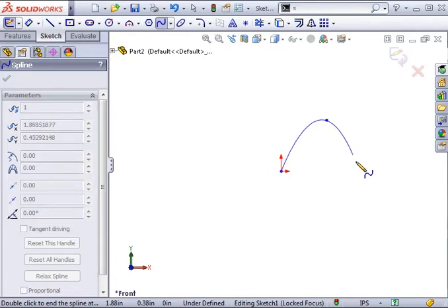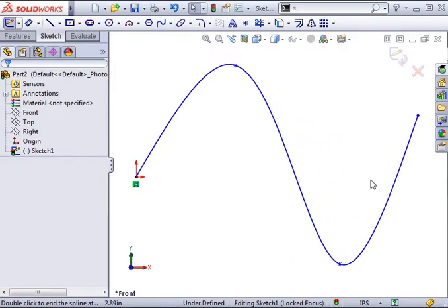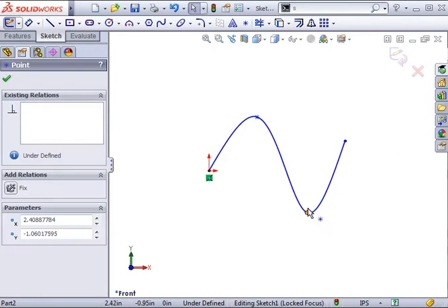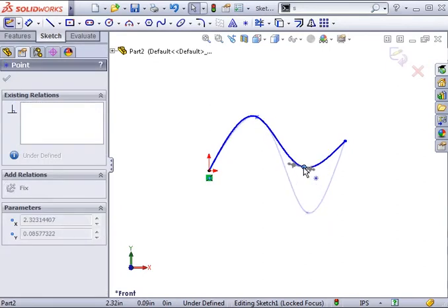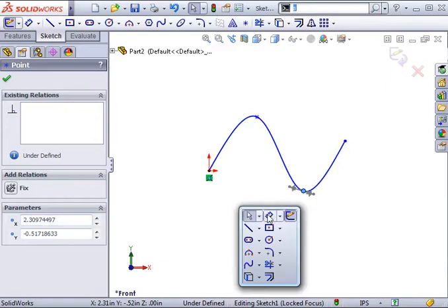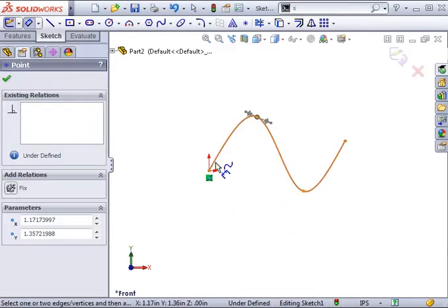You can leave the spline as an open contour, or you can close it back at the original point. Again, it's very flexible. To finish the spline, either double-click when placing the last point, or press the Escape key on your keyboard. You can click and drag the points on the spline to reposition them, and add dimensions and sketch relations between the points to further define their position.